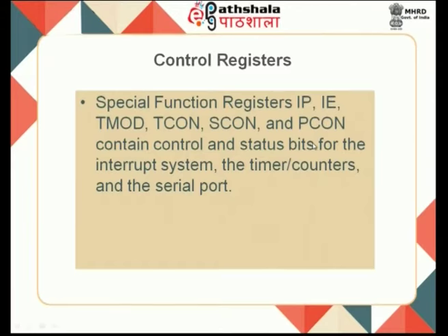So, when you are looking at the IE, we will be setting a particular bit which in turn allows the system to work on interrupts. The same way, when I am looking at timers and counters, some of the bits will be set or reset with your TMOD, which enables or disables these timers and counters, and the serial port communication is enabled through your SCON.